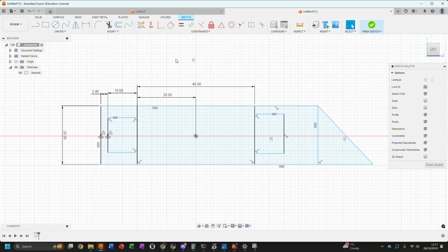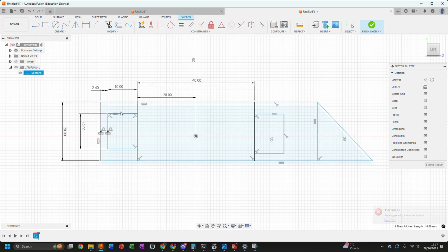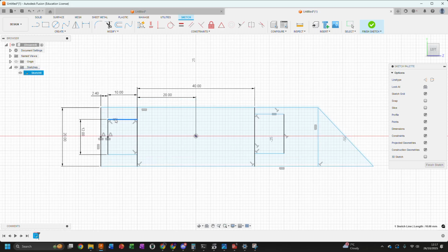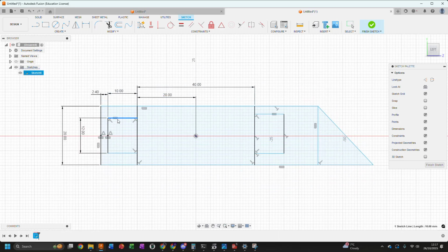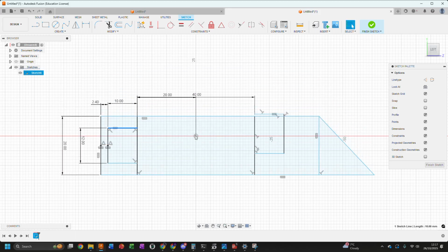So we haven't defined what that length is yet, so there's no point. So yes, this should be 12 millimeters. And this distance should be, okay, yeah, that is over constrained. Whoopsie daisy. Oh yeah, and we should probably make this whole thing central about this origin point here.